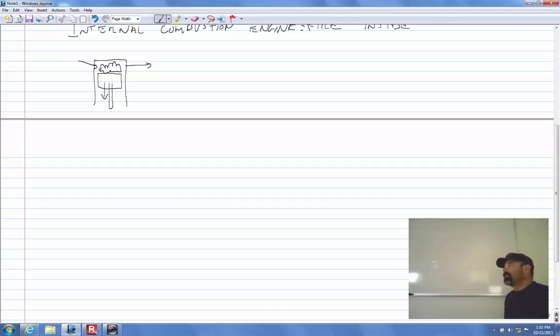If I were to put it on a rolling dynamometer, where you roll the car onto it, strap it down, and the wheels are on top of the same system as a big drum that the wheels spin, and it tells you how much horsepower it has, what would that 200 horsepower car have sitting on one of those dynos? Like 160. Probably, yeah, like 160 or something. You lose like 10 to 15% through your drivetrain.